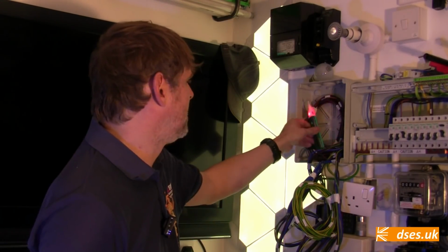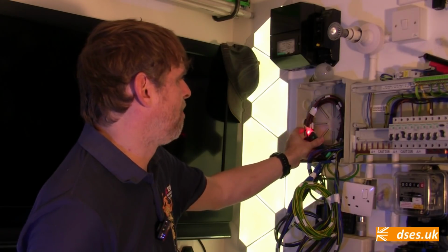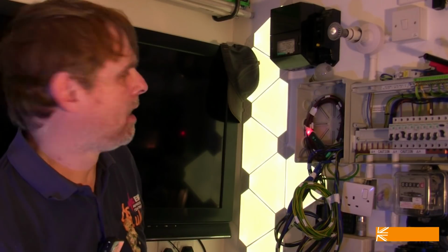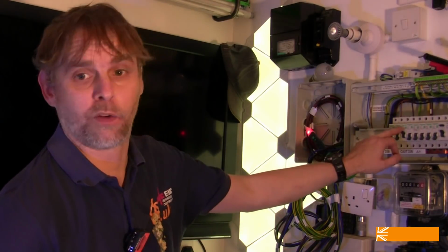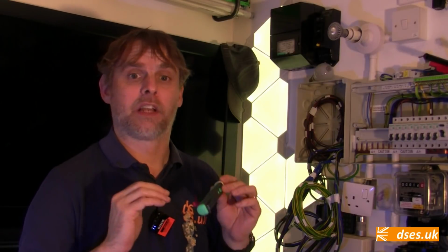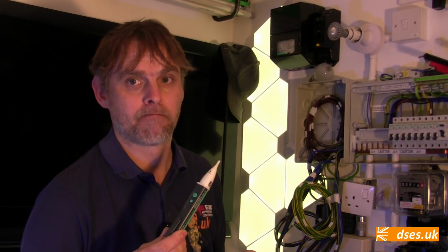If I reorientate this so that the antenna is near the live wire and the base of the thing is near a CPC, then I can happily walk away, as it's now capacitively coupled between line and earth without my presence. And it will continue to sound off reliably until I clock off the power. And this is one of the flaws with non-contact voltage indicators and why such cannot be relied upon for safe isolation. It only picks up a live wire if it itself is capacitively coupled to earth, and its efficiency is affected by how the person holding it or the location it's placed in has been grounded.